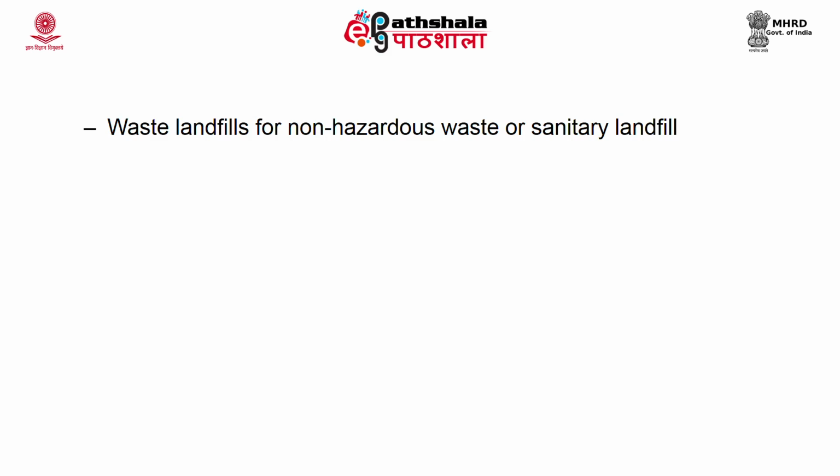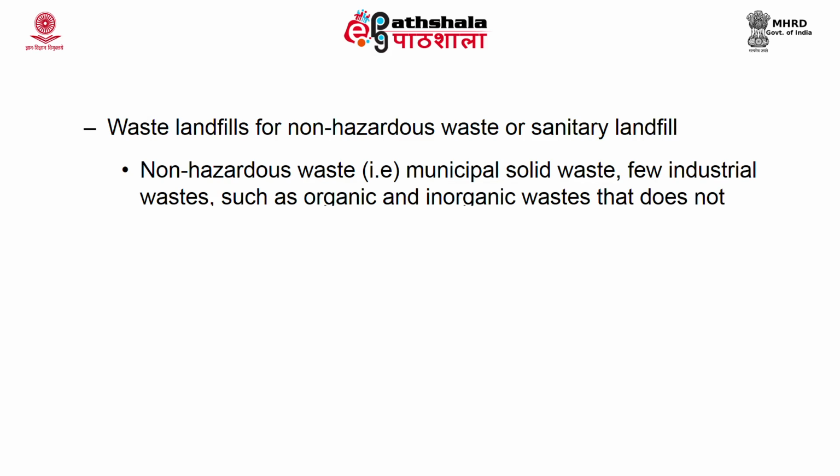Next type of landfill is for non-hazardous waste, or it is also called sanitary landfill. Mainly it is used for municipal waste, and non-hazardous means any waste that includes the municipal solid waste and a wide range of industrial waste such as organic and inorganic waste, provided that they are non-hazardous.